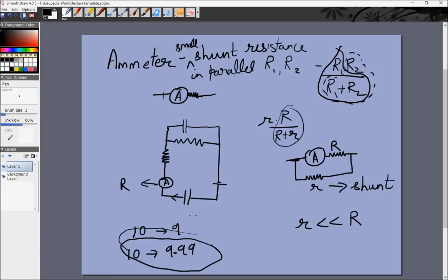What happens is, because in creating an ammeter we use magnetic fields, ammeters are generally very sensitive to current. So for example, a general ammeter might read a current between 0 and 10 amperes. That means the minimum current it can read is 0, obviously, and it can read a maximum of 10 amperes. If the current flowing through the wire is 100 amperes, then it will not properly function. So what if we really wanted to measure a current which is, we know, around 500 amperes? This thing works there as well, because when we say 0 to 10 amperes, that means the current flowing through this particular part of the ammeter has to be between 0 to 10 amperes.